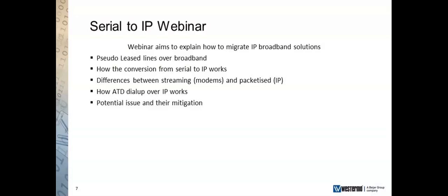We'll also look at how ATD dial-up works over IP. Those of you who've got systems which use ATD dial-up, they call a modem the other end of whatever kind. You get a connection, you pass data, you close the call, and then you move on to the next device and call again. We can show you here how that technology can be migrated, again, without the need to change the actual end equipment. You can just use the existing equipment, but change the media in the middle, and everything works, or should work, as it used to.